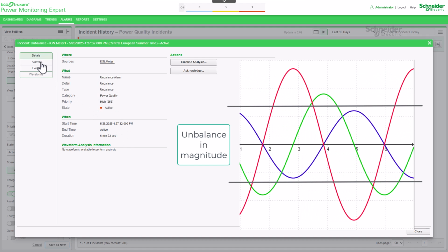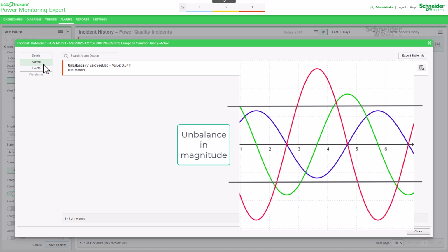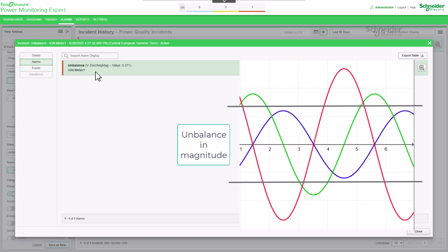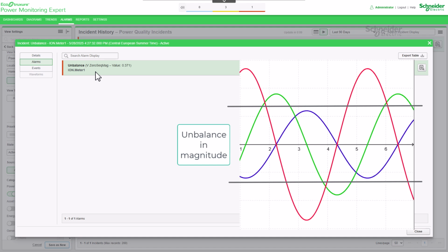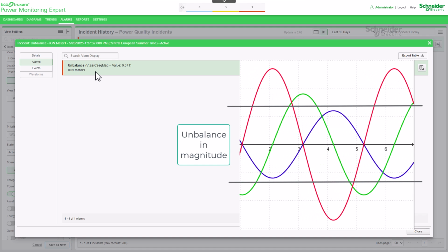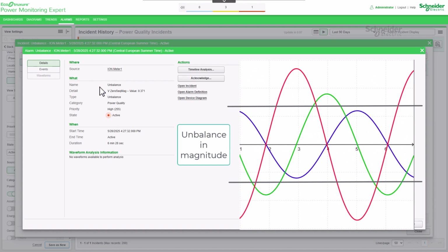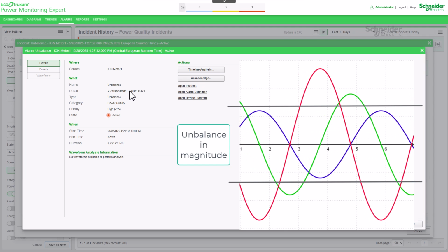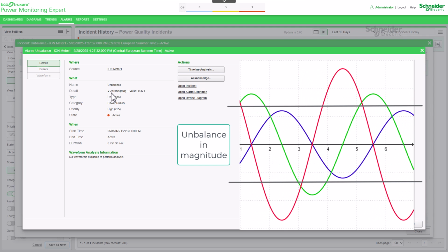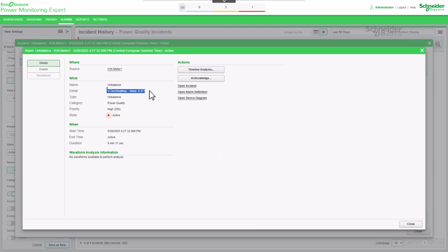Voltages are rarely exactly balanced between phases. However, when voltage unbalance becomes excessive, it can create problems for polyphase motors and other loads. Moreover, adjustable speed drives can be even more sensitive than standard motors. Voltage unbalance is primarily due to unequal loads on distribution lines or within a facility.